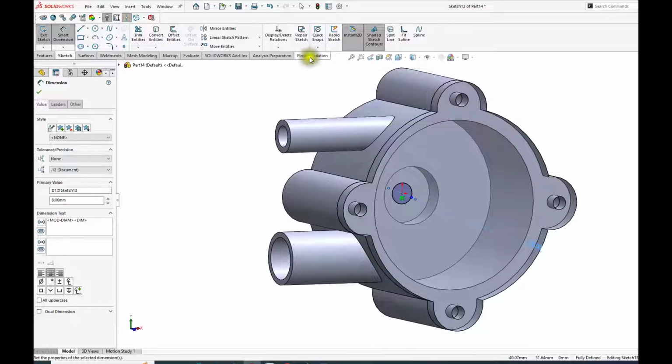If you're gonna do flow simulation, that needs to be plugged at a later time. That's during flow simulation. There's a technique that you can plug this, and this. I don't care about this one because there's no flow through them. But there's flow through here, inside here. So you want to be sure that this one is plugged, this one is plugged, and this one is plugged. That's part of flow simulation, which is another chapter.